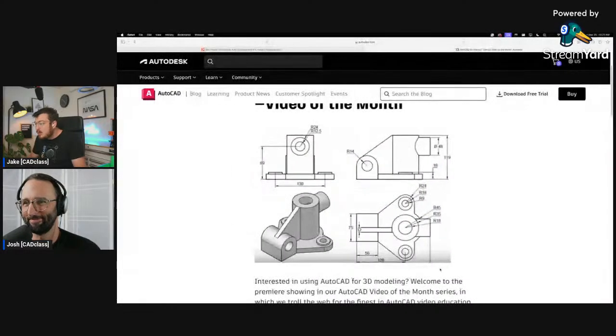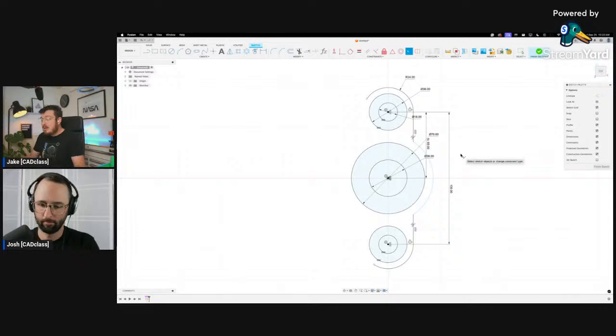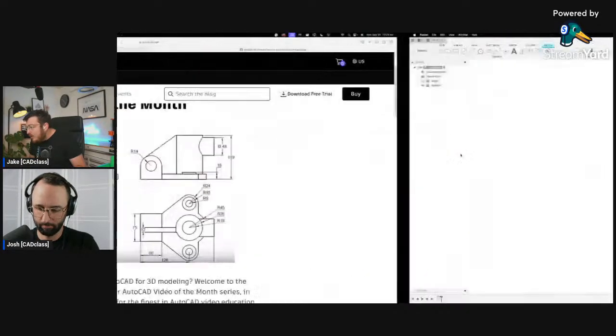Okay, so then those are going to go angle, vertical to that. So I've got 2 completely vertical lines that are tangent from those external arcs, but aren't necessarily tangent to this piece right here. So I'm going to make them both vertical and then collinear as well. Usually adding constraints is much faster than adding all of our dimensions.